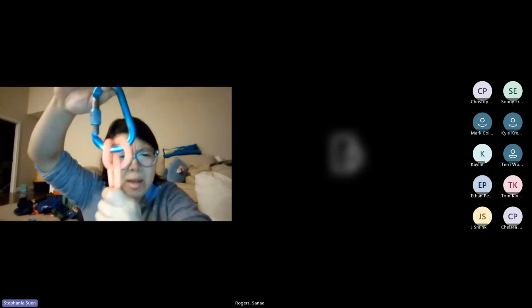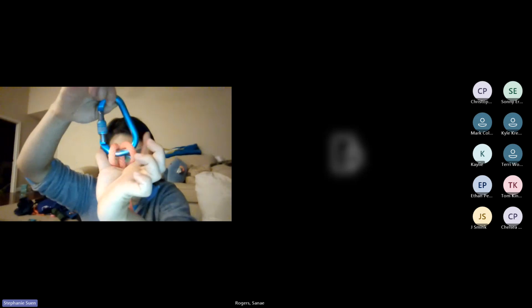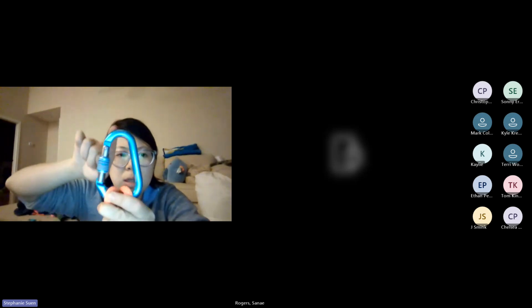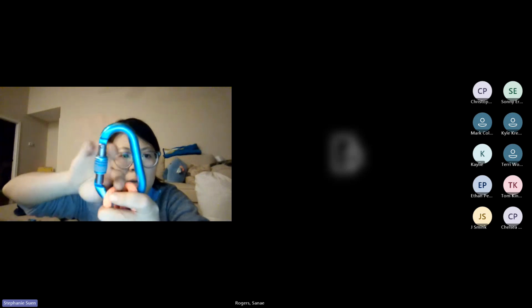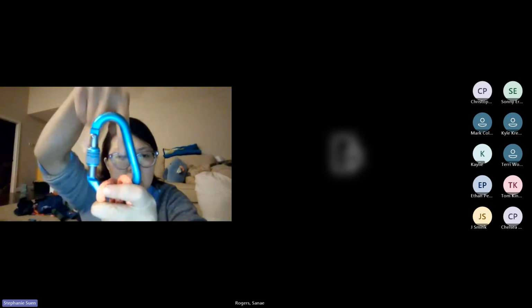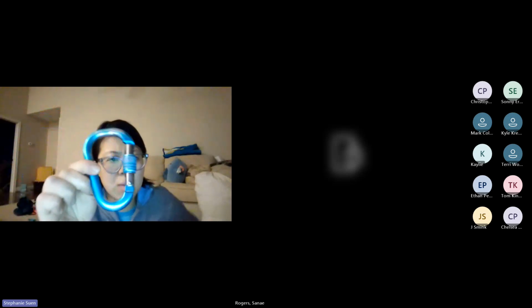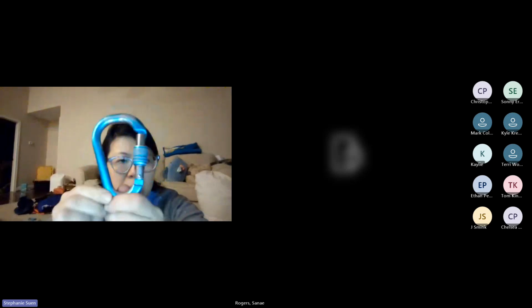But as this rope has two contact points on the carabiner, it's preventing that tri-load by having this wide pear shape. And the force is along this imaginary axis down the center, so it's loading these two legs because of that wide head. And that's sort of really why this shape of carabiner was developed.